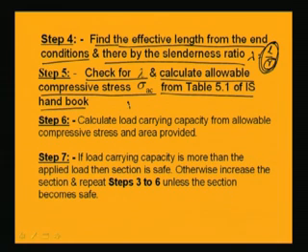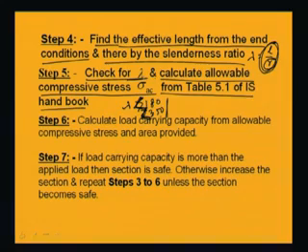First we will check whether lambda is within 180 or 350 as per the codal provisions or not. The value of lambda will be either less than 180, or less than 350, or 200 as per the codal provisions. So, we will check that the lambda calculated, whichever we are getting, is coming under the codal provisions or not.